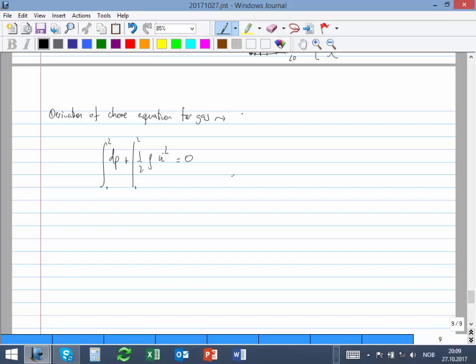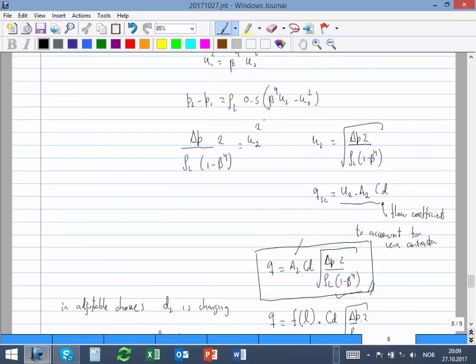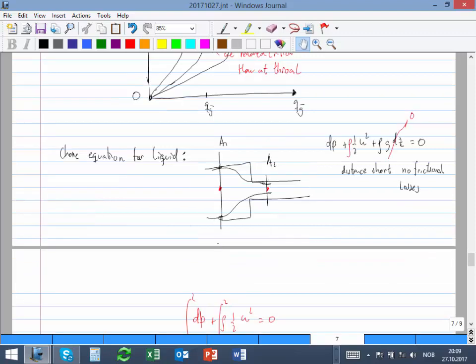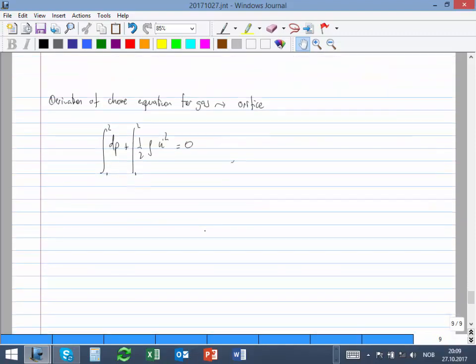Basically, this is also the orifice equation, because we are assuming that you're looking only at this part. So really, if this is very short, this equation is also good for a very short orifice. We are assuming in this development that after this point, the pressure stays the same. You have no recovery of pressure after that point. That's the main assumption of this model. And you can try to improve it, but that's the main assumption.